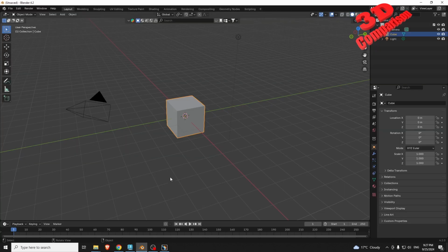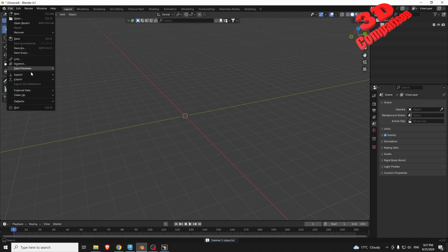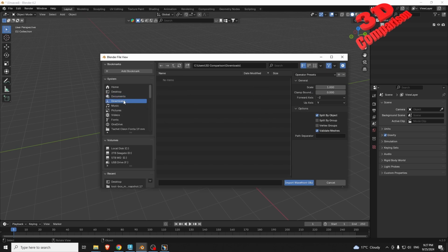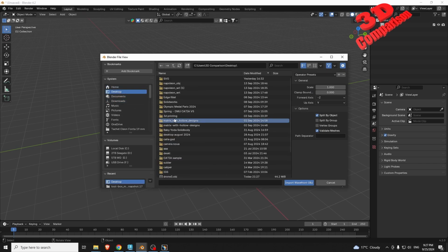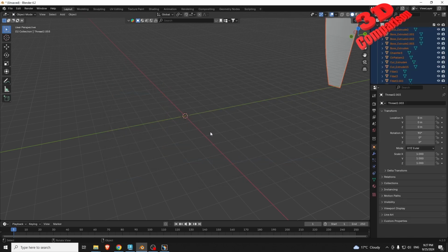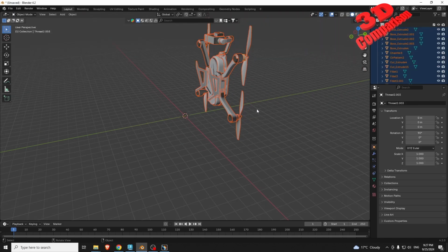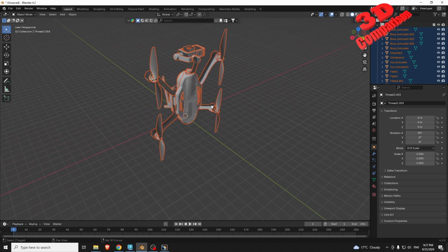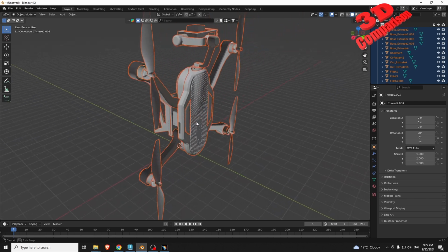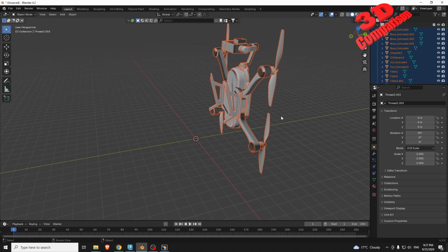And now within Blender, I will import that file. I didn't import it directly within Blender because Blender doesn't import step files without paid add-ons. But we see over here that we can now import OBJ. And the file previously converted, which will be drone3 obj, we import as follows. So we see the model over here. This will be quite large, so we need to be aware that this has been scaled 1,000 times. So when we're going to import it back to CATIA, we should make this smaller.